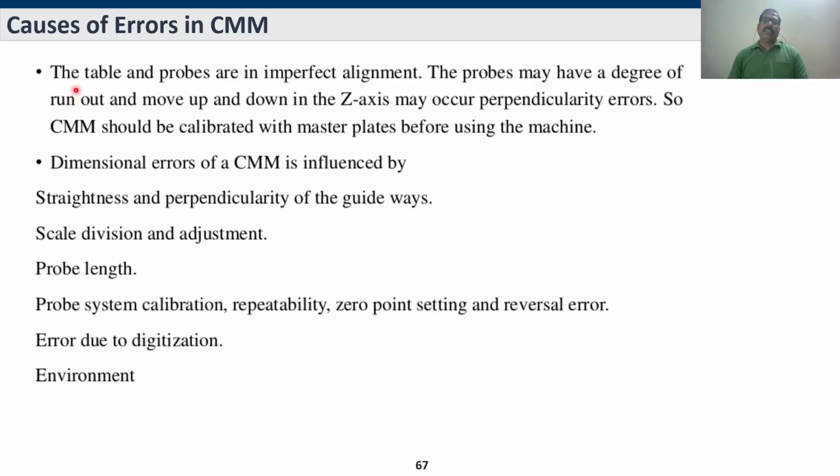In terms of industry, they will mostly keep the CMM inside a controlled environment. In our lab also, you might have witnessed many people moving here and there, opening and closing the door, and machines running in another room, like CNC machines or milling machines, kind of conventional machines also running. So all this vibration will affect the positioning errors or accuracy of measurements. So you always need to do some error calculation or calibration. That's what I always used to say.